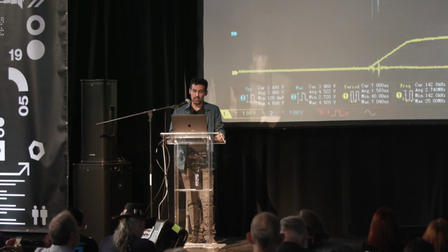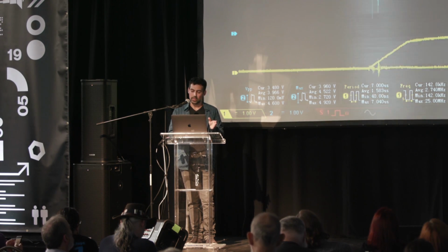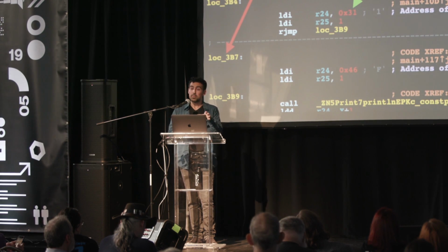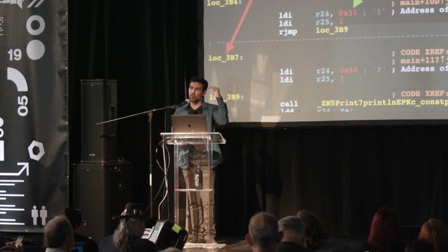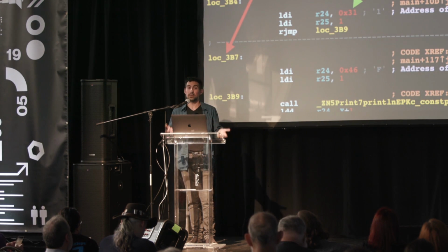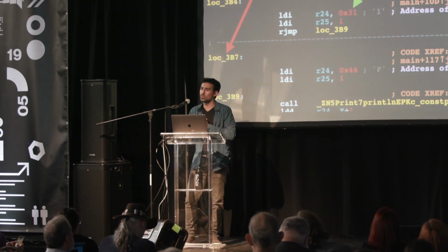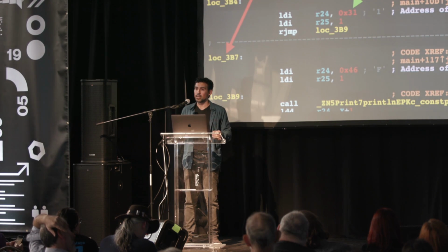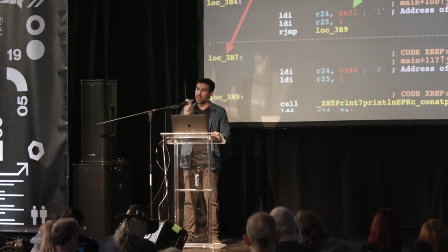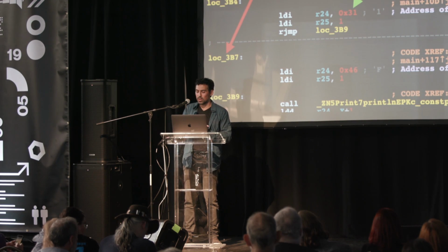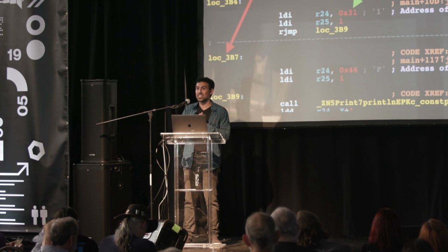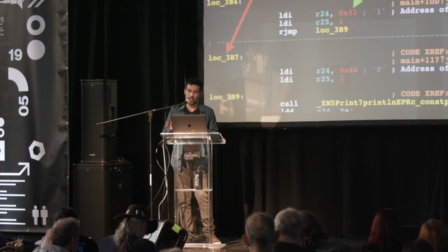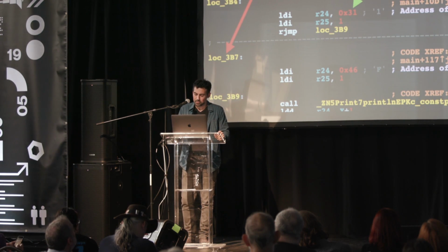Here we can do essentially a voltage glitch, and all you're doing is removing voltage from part of the CPU for just a moment as it's performing that instruction. Instructions take time, so you can perform a clock glitch where you send a clock. Let's say your Uno expects maybe a 16 megahertz clock, and it's going to do everything on a rising edge. So if you can send a rising edge, but not give it the time it needs to execute everything, because everything is sequential logic here, you can then skip that instruction.